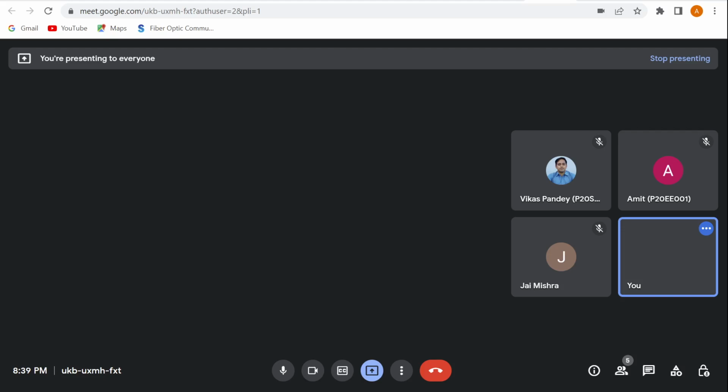So X(w) equals e to the power minus j omega t upon minus j omega, evaluated from minus T by 2 to T by 2. So the integral equals minus 1 upon j omega. You have to take the integration and solve this equation. It will be of the form a minus b, so we take the complex exponential: cos a minus j sin a minus cos b plus j sin b, and it will give you the solution 2 sin(omega T by 2) upon omega, or 2 sin(2 pi f T by 2) upon 2 pi f.